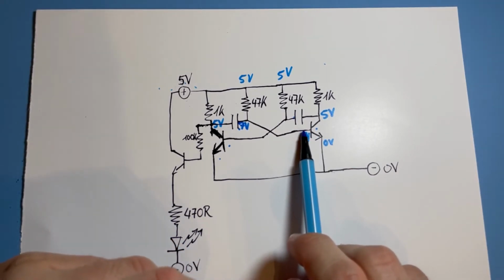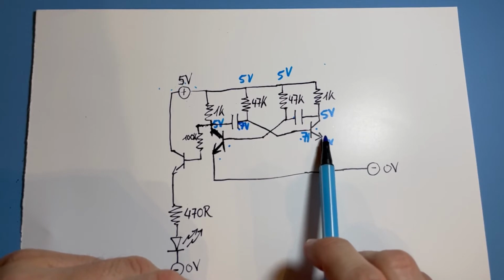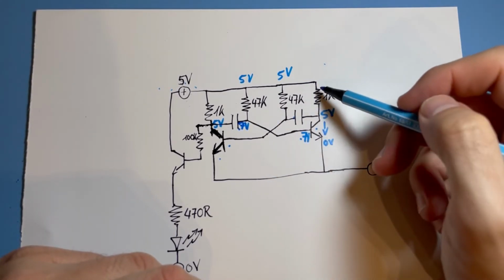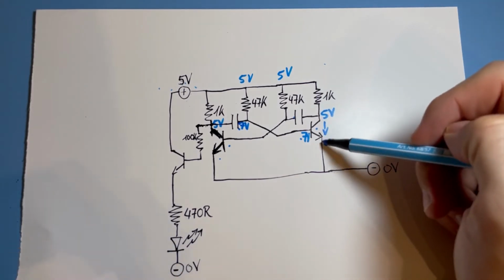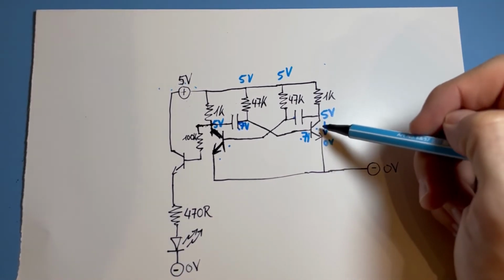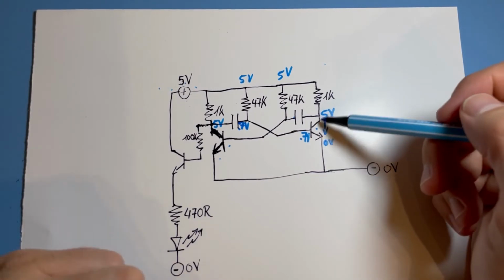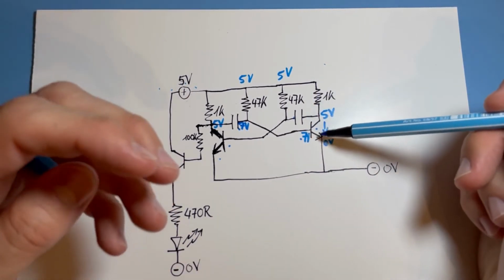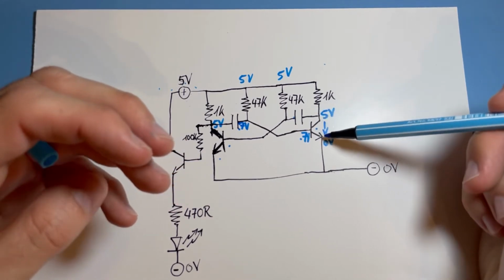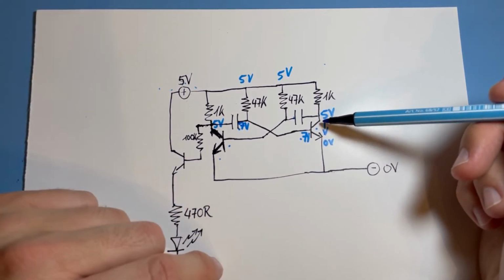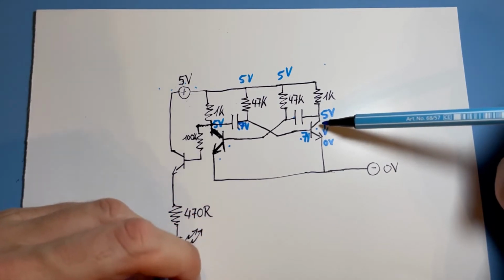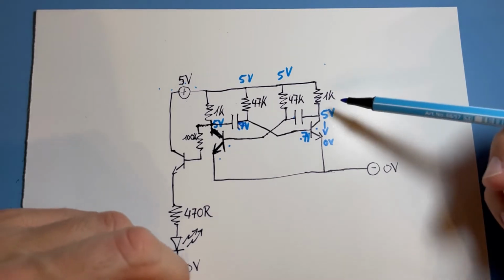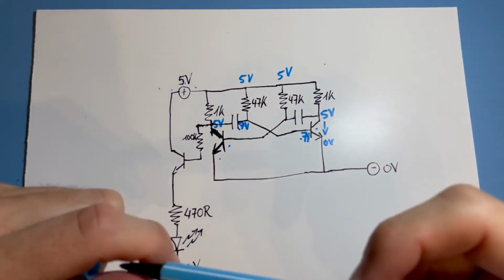And so this transistor starts to conduct first on the base emitter, and because of the current through the base to the emitter, also this path here is opened. So the regular collector to emitter path of the transistor, because that's how a transistor works. Once you have current through the base to the emitter, then also the collector to emitter path starts conducting. And what happens is now the second stage.